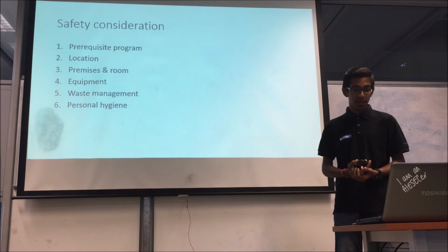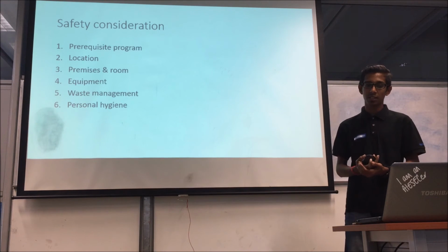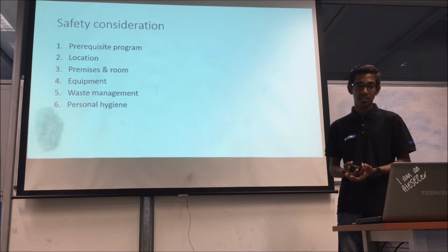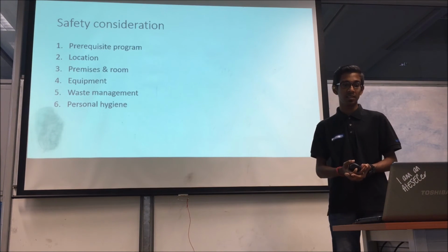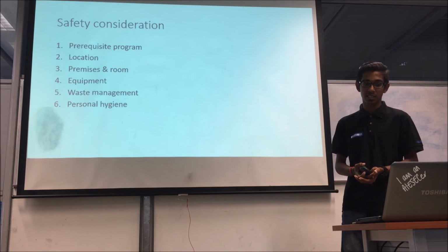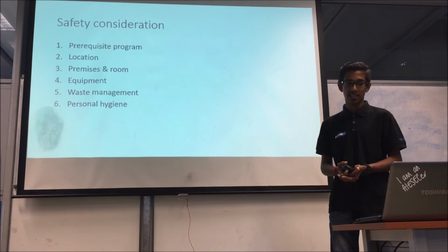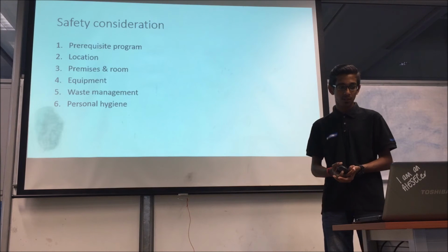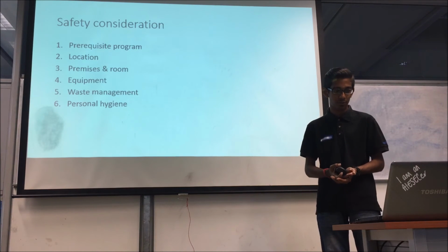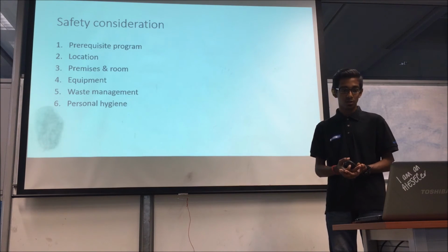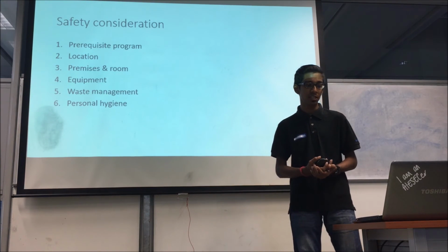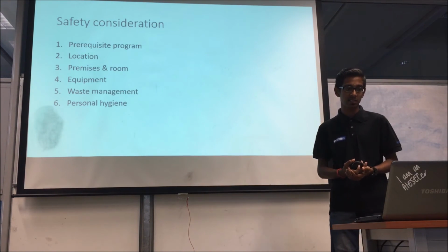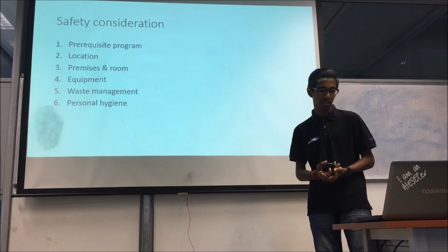Alright, next is waste management. So the company needs to have its own waste management treatment plant along with proper drainage and storage system, which is a combination of activated sludge method and aerobic treatment that contains equalization tank, gravity settle unit, flocculation unit, coagulation unit, cube settler, effluent discharge and sand bath. So the physical, chemical and biological specification based on national standard of entering waste and discharging system is also checked regularly.